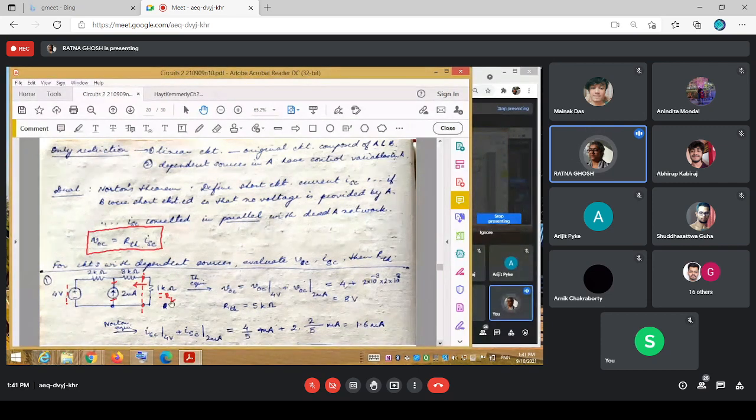So finally you will draw it out as a 5 kilo ohms with a proper polarity. So this would be the 8 volts, and that would be 5 kilo ohms. So this would be the equivalent resistance representation. This would be your RL. So you must provide this one, else it is not complete. So the equivalent Thevenin circuit is this.